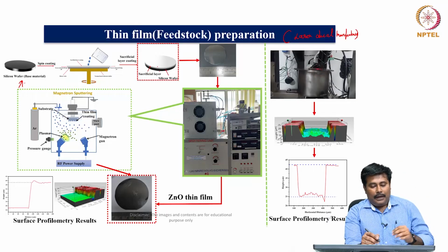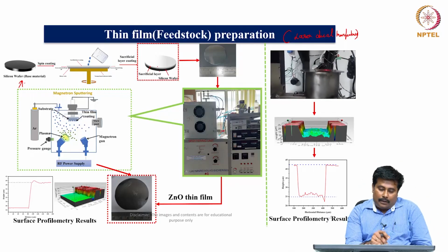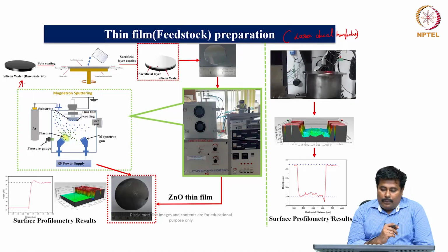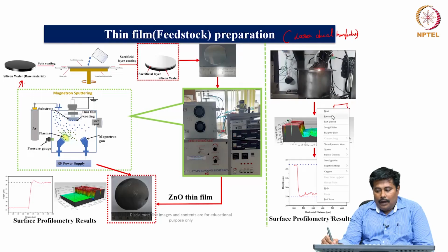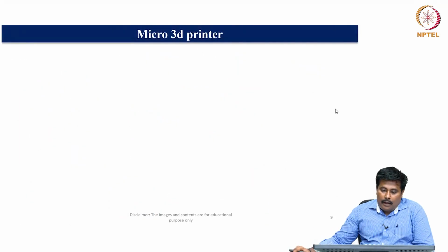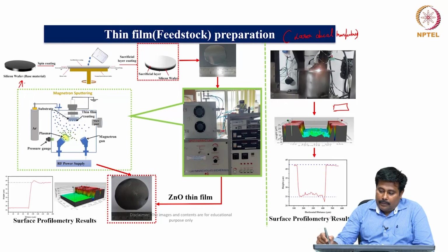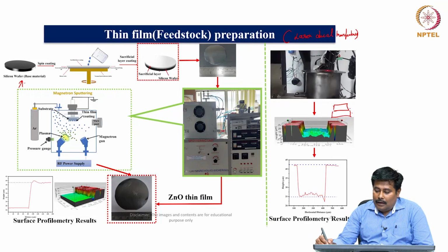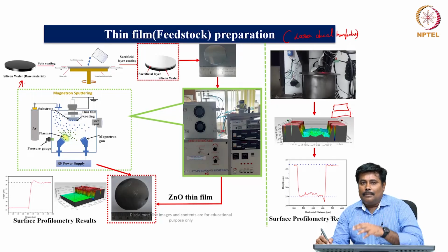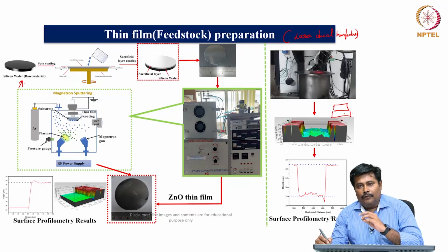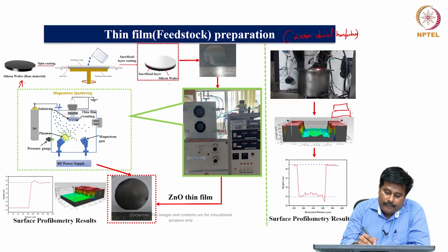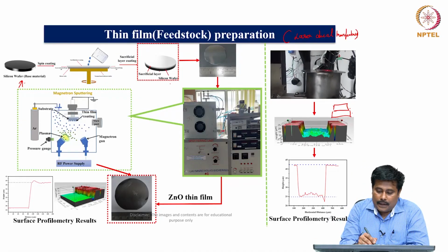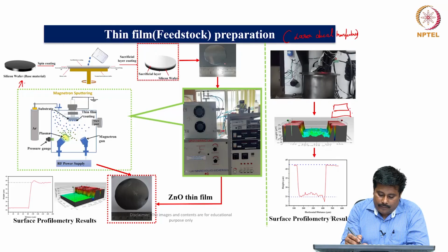Here in this particular part, we need to observe one important point. The donor material should be transparent to the laser. However, the sacrificial material should absorb the laser completely so that it can be helpful for ejecting the particle in the forward stroke. Now, this is the sacrificial layer which is coated over the silicon wafer substrates.